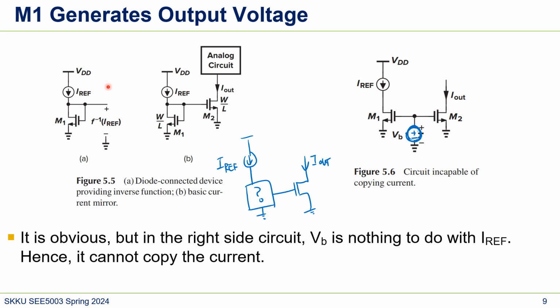And then if we come back here, this is what we discussed, the diode connection of NMOS over this IREF. So now this voltage is a function of IREF, right? Because IREF goes here, and this will automatically set the voltage here. Let's think about it in this way, in terms of a timeline, I mean from a transient point of view.